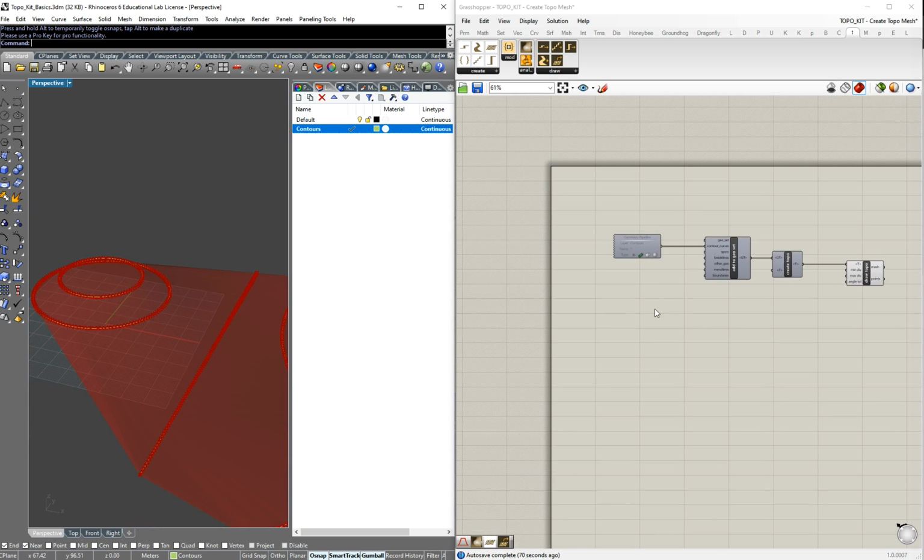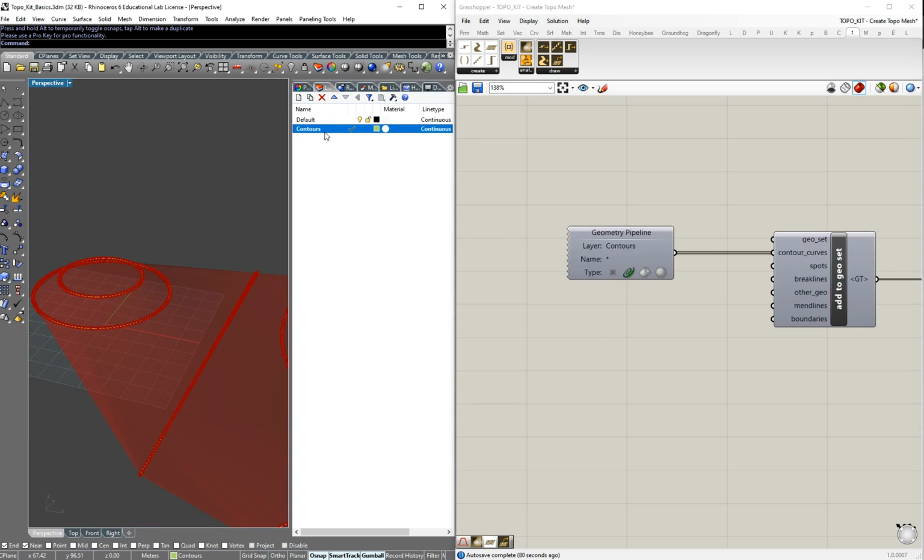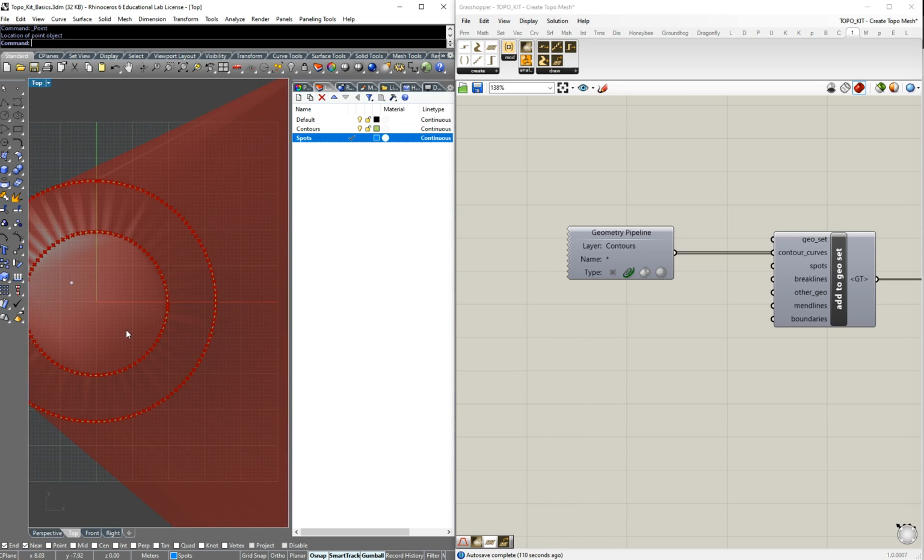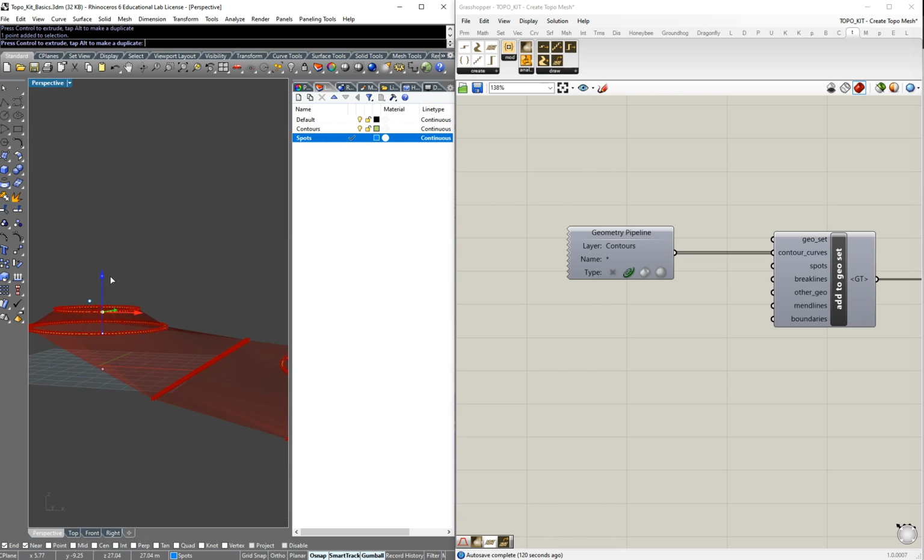You can also use spots. By spots, we mean, let's say, specific points in a layer. So let's put these spot elevation. Let's put the spots just to make it simple. Select, choose a nice color to identify the spots. Okay, and then click here with the point. Select this current layer and then go to the top and select a couple of spots. Here we go with another one and perhaps another one here. Let's go to perspective. Now the points are here. We can select a specific height, for example, this below or like that. And this one, for example, a bit down.